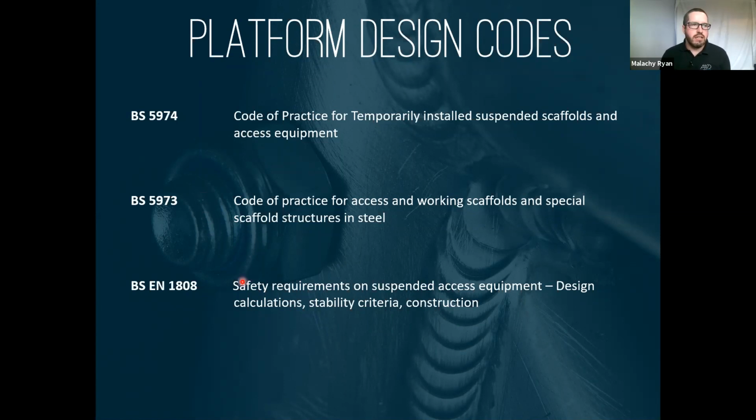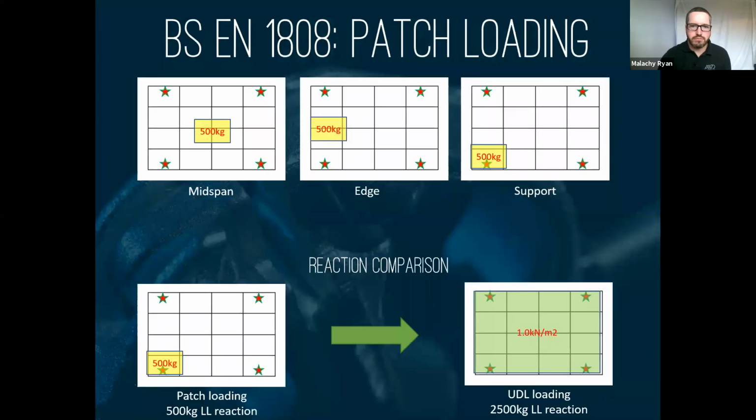And 1808 gives you a different scenario where you've got patch loads. And I'm just going to go through patch loading now for those of you who aren't familiar with it. So patch loading is where you take a concentrated load and apply it in the most onerous locations on the platform to get a design to work.